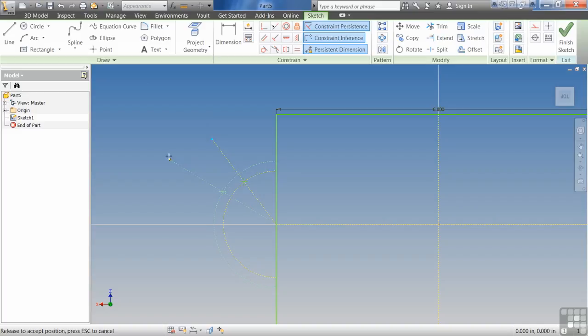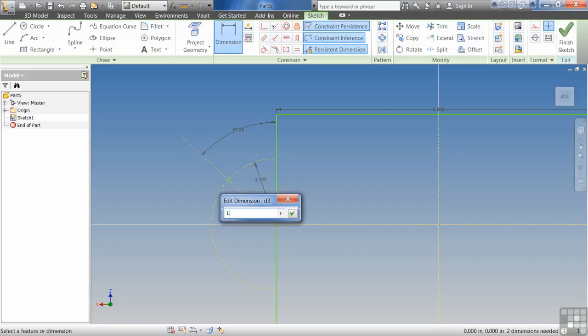This is probably the most common type thing I use construction geometry for. So I'll come in here and I'll dimension this, say 47.5 degrees. Then I'll dimension my arc. So now, where those two intersect, maybe it's 2 knowns I have.